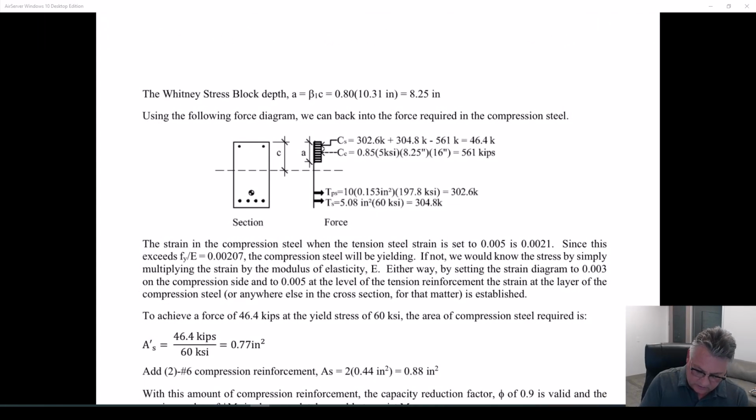So with that neutral axis depth, a is beta 1 times c, so I know what a is. Now you can see that this analysis is telling me what the concrete force is. If a is now a given, because c was a given, and that was all based upon the strain required for tension controlled, I now know what the force in the concrete is under that situation. 0.85 f prime c a times b. So now I've got a force in the concrete.